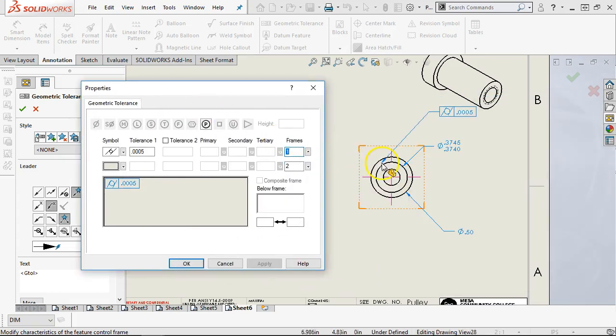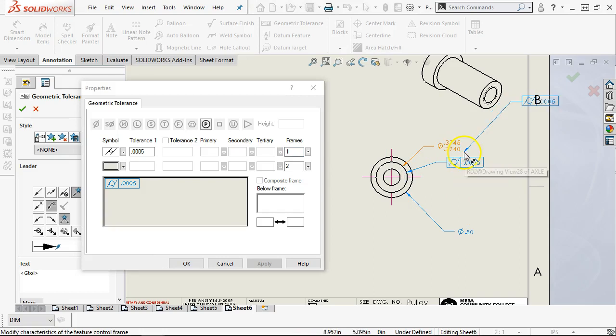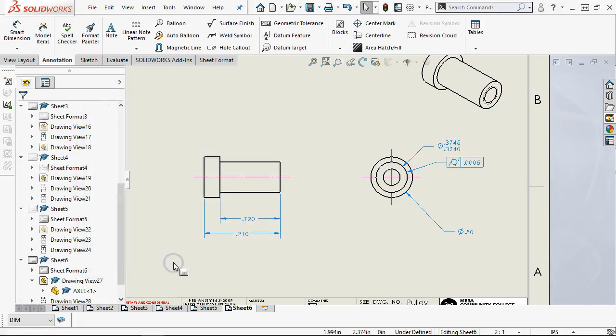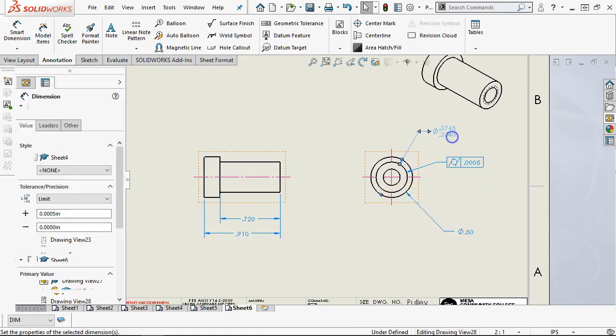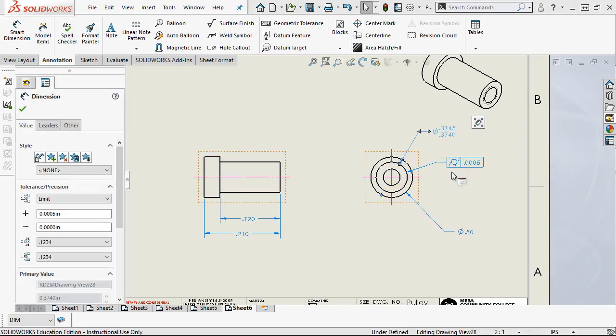But to make the argument stick, if I apply it to the same cylinder that I have the dimension on, that should instantly raise, hey, this is in conflict. Something's going on here that I need to pick. So on the one hand, this dimension makes a lot of sense in the ability to pull that number, but I really need this to be a basic dimension, even though the cylindricity isn't really modifying, but I need to put it in reference to that number.